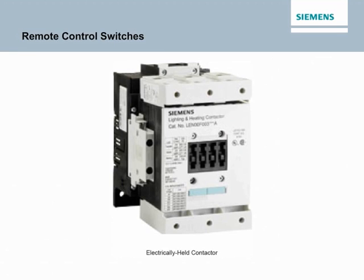When an application requires remote control switching of loads, an ASCO 911 or 920 mechanically held remote control switch or Siemens LEN electrically held contactor can be mounted in a separate cabinet as a main disconnect.